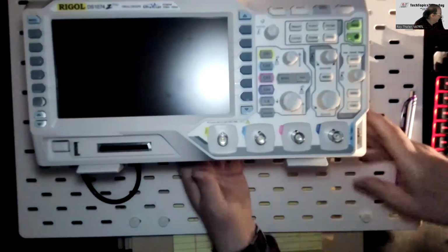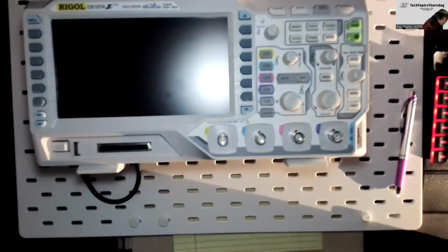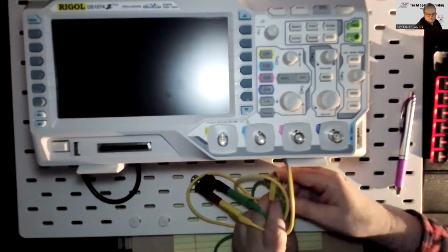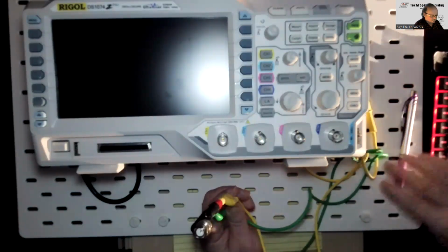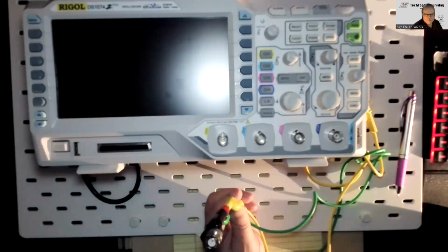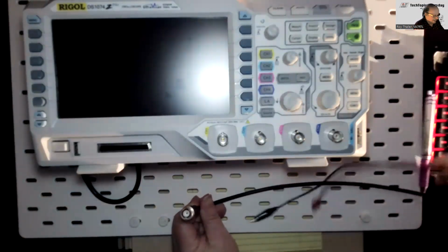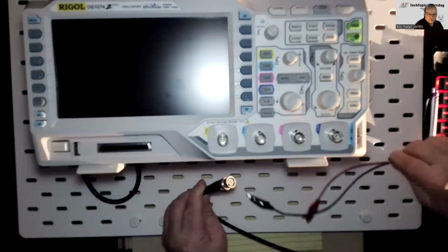Before we turn it on, let's look at some probes. You have a choice of a number of things. For example, you can have a BNC connector, which you connect to the scope like this, and then some leads with alligator clips at the end that you connect to your signal. This can be used for low frequencies, but it's likely to pick up a lot of noise. You can twist the wires together to reduce the amount of noise you pick up. The other way is to use a BNC type of cable, with either a BNC at both sides or an alligator clip on the other side.